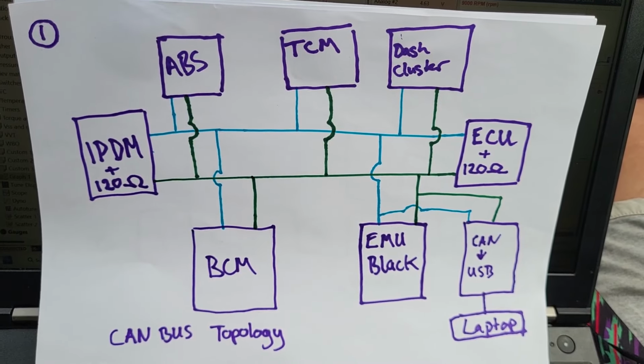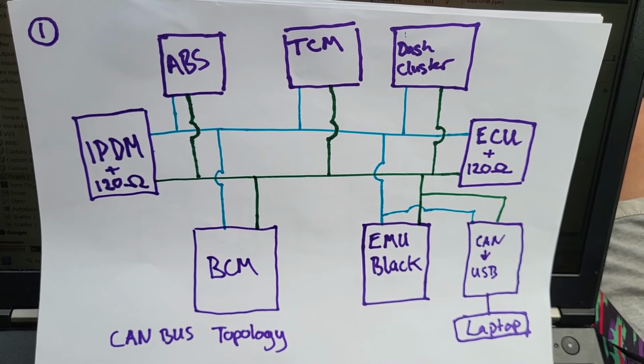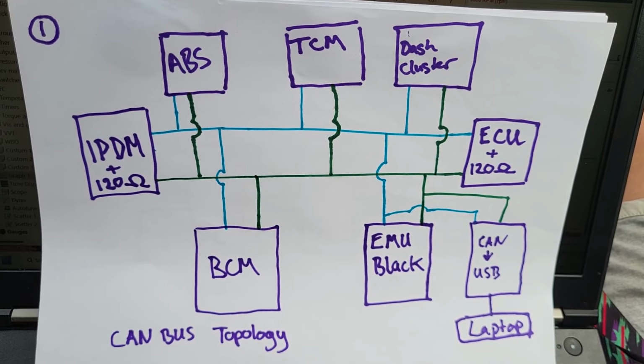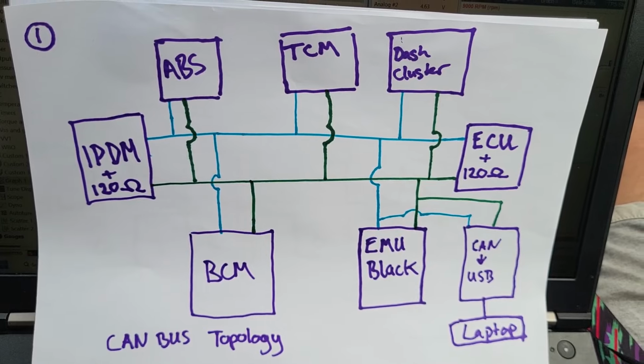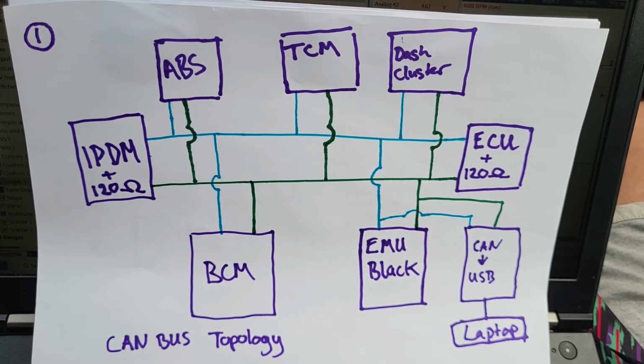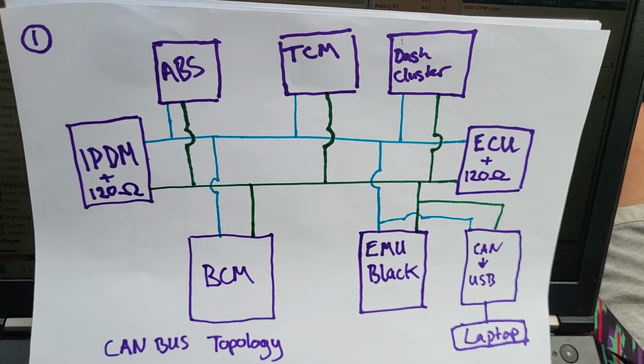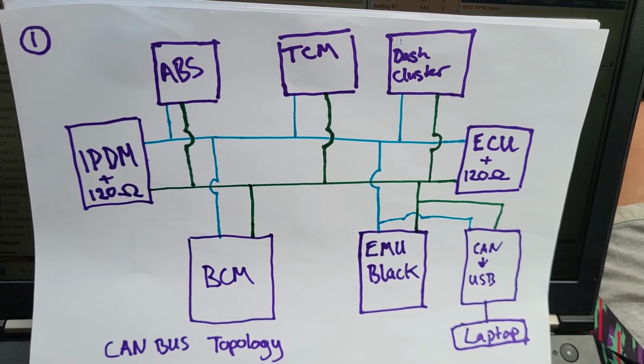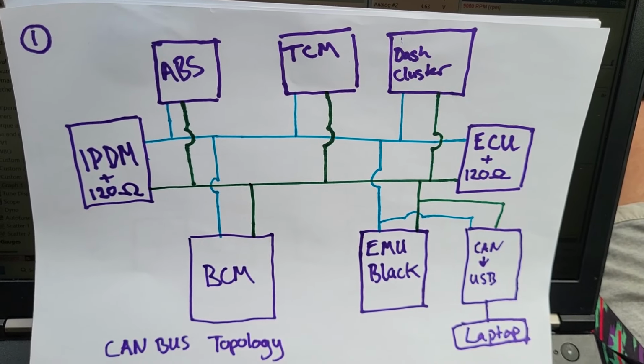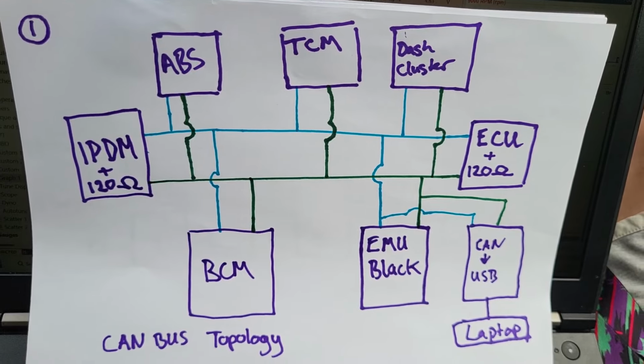Basically you divide by 2 and it should be 60. So a key way, if you're ever troubleshooting a CAN bus network, is if you do that test and you get 120 ohms, that means you're missing one end of your network. You're missing a key part of that bus.